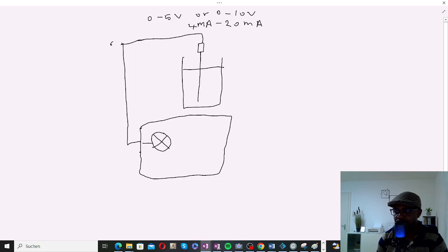What it does is that this signal that is coming from the sensor is sent to this comparator, and here could be a plus, depending on the convention you are using. Could be a plus, and here could be a minus. And then the signal that comes out now goes to the control head.